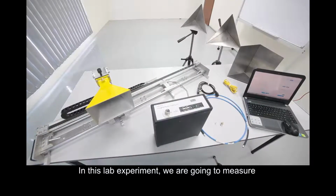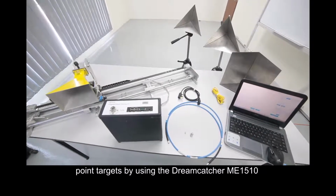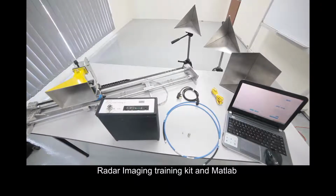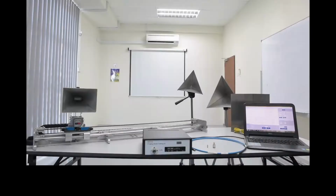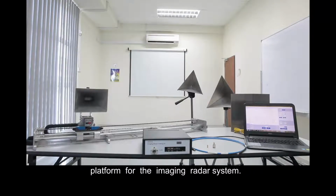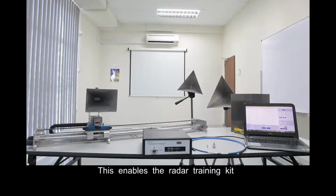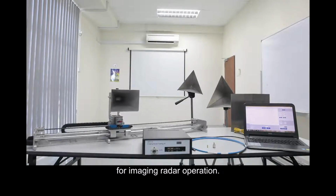In this lab experiment, we are going to measure point targets by using the Dreamcatcher ME1510 radar imaging training kit and MATLAB to perform azimuth compression. The ME1510 training kit consists of an embedded imaging radar module, linear scanning platform, horn antenna, corner reflectors and PC-based GUI software. A linear scanner is provided as the moving platform for the imaging radar system. This enables the radar training kit to perform a translational scanning mechanism for imaging radar operation.